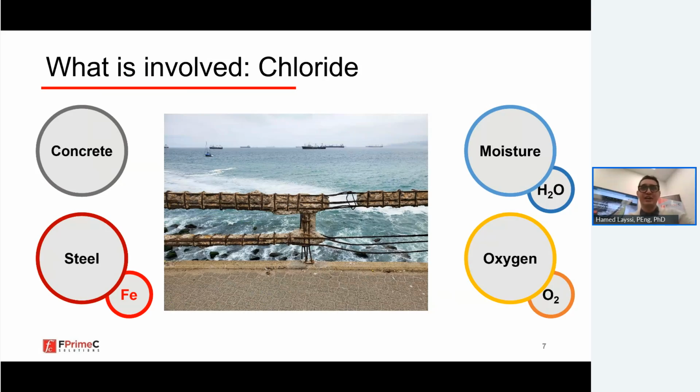That is why I called this photo that I took a few years ago "reinforced air." The corrosion has progressed so much that you barely see any concrete left. It's a bunch of rebar left there. When rust forms on top of rebar, it expands. The expansion exerts force in reinforced concrete, and it induces enough stress to degrade the concrete. If left untreated, it can progress as badly as you can see here.